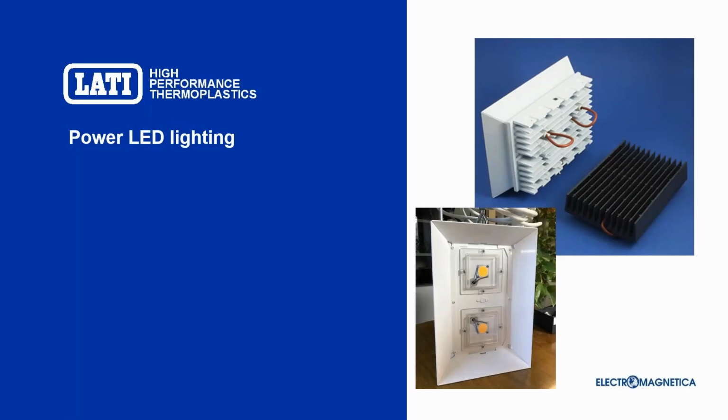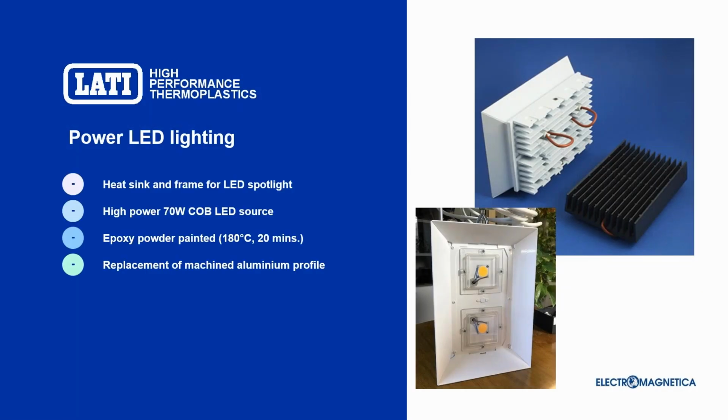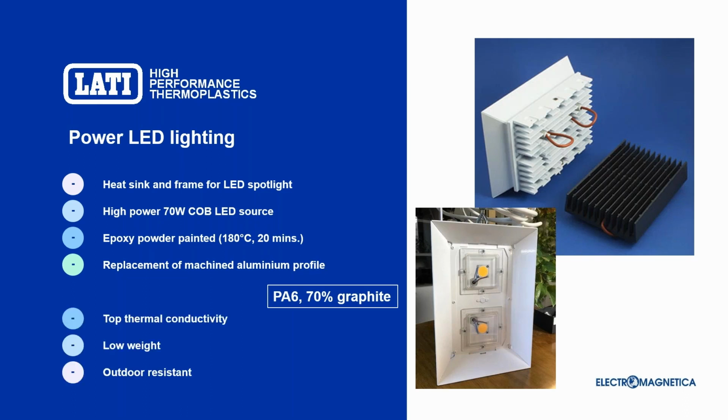This case history is again a spotlight, but a significantly different one, because this is an industrial spotlight. The thermal power to be managed was really huge, really high. This is an aluminum replacement project, and the customer wanted the part to be white, so colored. So we selected a polyamide 6 with 70% of graphite. This is the compound which offers the top thermal conductivity.